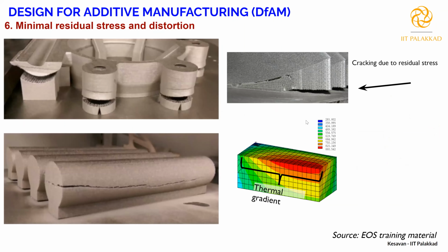If you don't take care of the residual stress, what happens? You see here, all this component failed because of the residual stress. You did not apply any external load, right? You did not pull it. You printed it and kept it on a table, and it failed by itself without applying any load. That's because of residual stress. And as I said, it's because of uneven expansion and contraction, or a lot of heat input in one direction. Those things will give you such cracks due to high residual stresses.